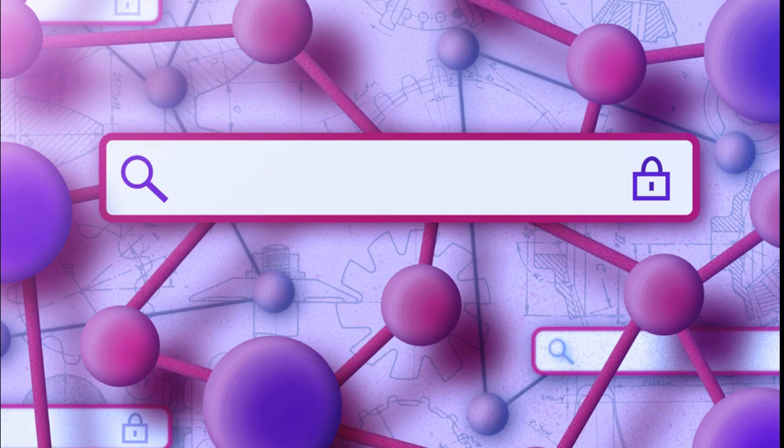A deep neural network consists of many layers of interconnected nodes that process data. Typically, the output of one layer becomes the input of the next layer. Data are grouped into units called tiles for processing and transfer between off-chip memory and the accelerator. Each layer of the neural network can have its own data tiling configuration. A deep neural network accelerator is a processor with an array of computational units that parallelizes operations like multiplication in each layer of the network. The accelerator schedule describes how data are moved and processed.